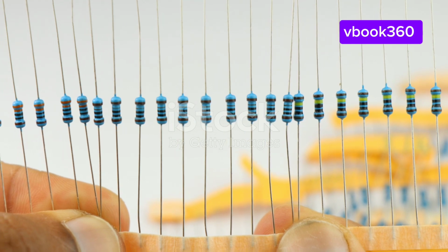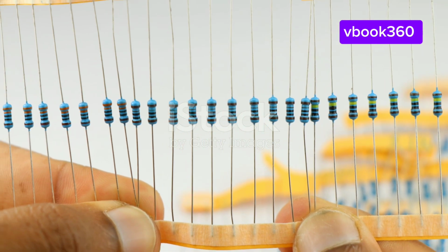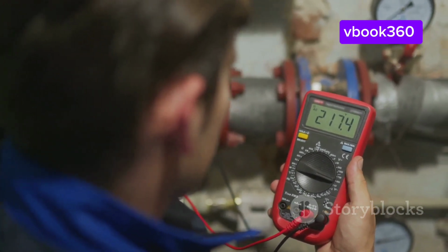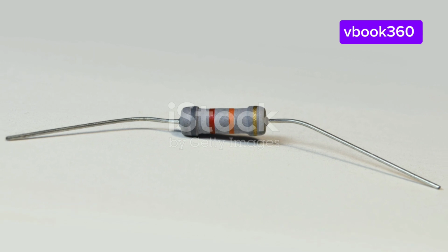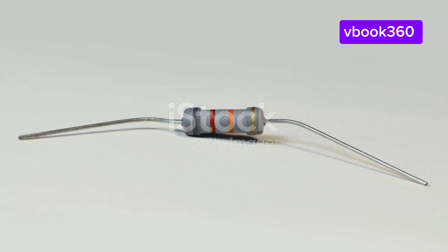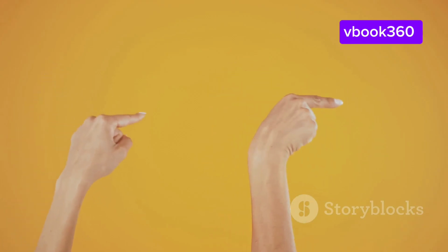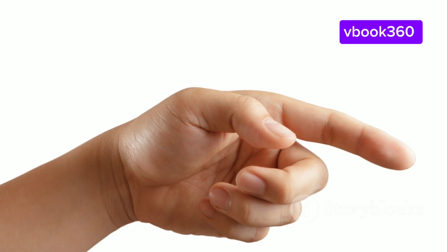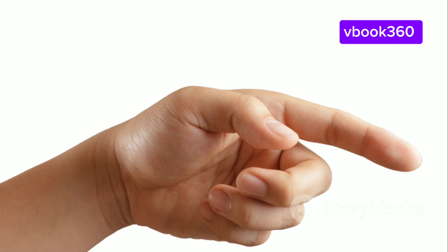While the resistor color code system is relatively straightforward, even seasoned electronics enthusiasts can make mistakes when interpreting these colorful bands. Let's explore some common pitfalls and discuss strategies to avoid them. Incorrect orientation. As mentioned earlier, reading the color bands in the wrong order is a frequent error, especially for beginners. Always identify the tolerance band, either gold or silver, first, and read the remaining bands from left to right, starting with the band closest to the resistor's edge.